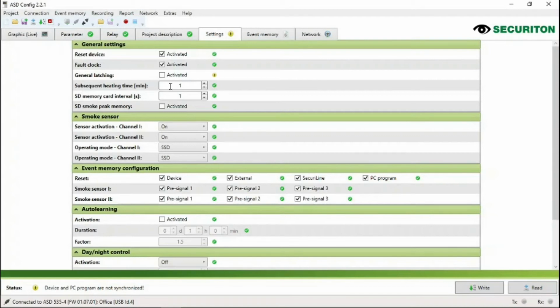Heating time, that's for freezer rooms. You can have a heating probe in each sampling hole, and when the aspirators are seeing a drop in airflow, it will actually heat those sensors. You can set it for 1 minute, 2 minutes, and so on. Also, something I haven't come across a lot with the way we install sampling tubes, actually it's not needed.